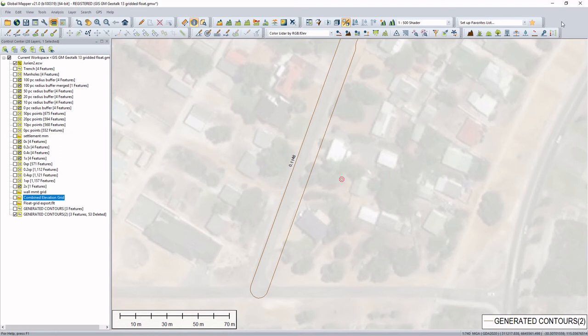And this is one of the powerful things about Global Mapper, certainly I find really useful, is that when it creates a grid, it can create a grid for elevation, for slope angle, and for aspect. And you can export each of those, turn them into vectors, and query them against other vectors in your plan.